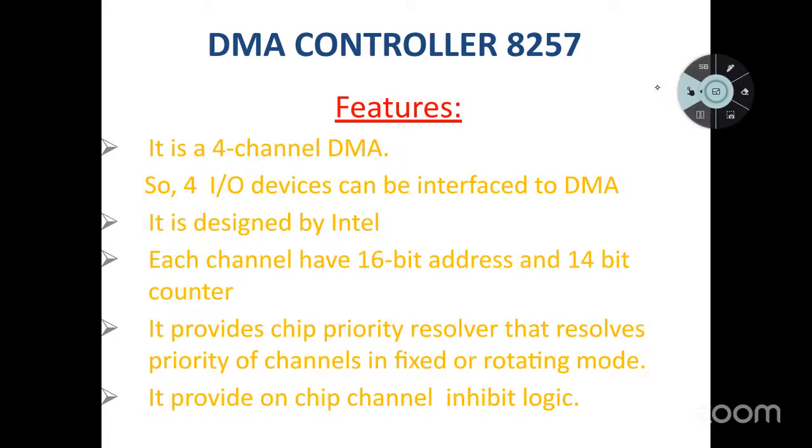Like the data bus, the 8257 has data lines. The same data lines are connected to the 8086 microprocessor. Processor communication happens only through the data lines and some special control and logic pins, the read and write logic pins. Data can be transferred between the 8257 and the 8086 using only the data bus. So the data bus is connected.